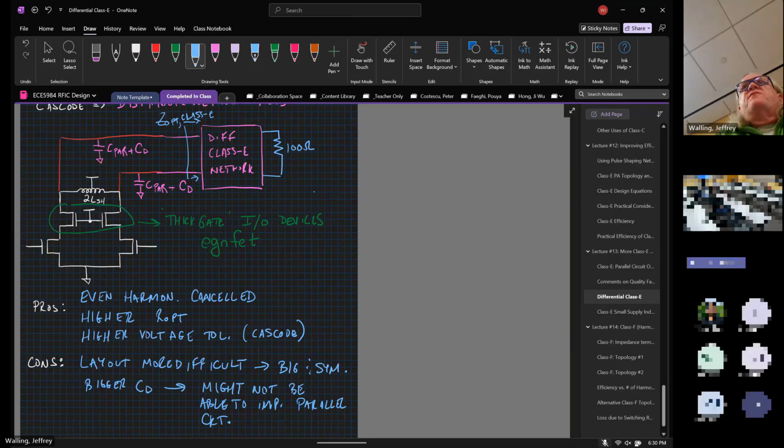It was by one of Paul Gray's students. I'll just see if I can dig that paper up. But we're not doing it to cancel the voltage spike. In this case, they actually are using it as a boost, because if you cross-couple the capacitance, the rise in the drain voltage on the one side can be used to kind of boost the gate voltage on the other side.